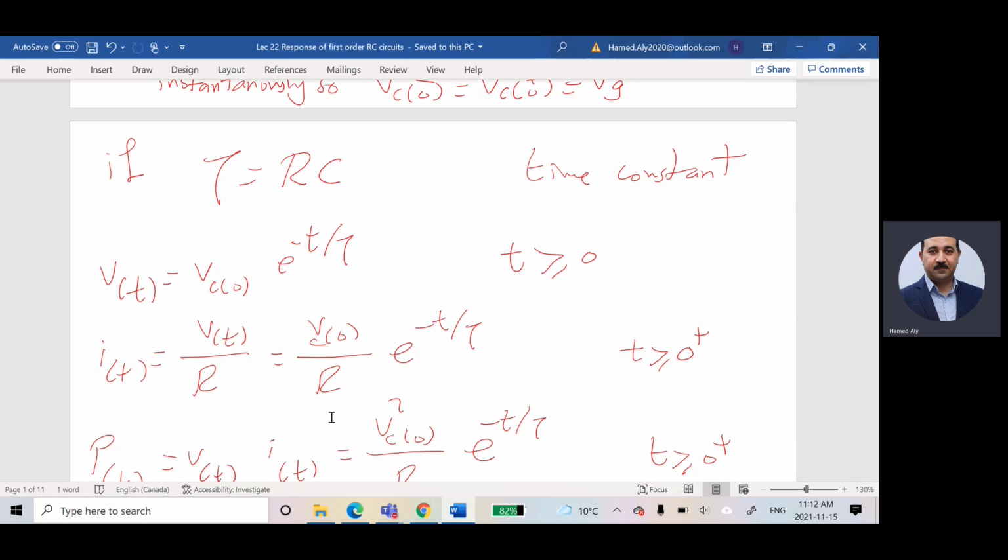But after moving the switch, right now, the voltage characteristic is changing. I have a voltage across the capacitor, but by the time, the voltage value will be changing because of this charging. As if you have variable voltage, not constant voltage. That's why, in the second case, after moving the switch, the capacitor is not open circuit. Why it is not open circuit?